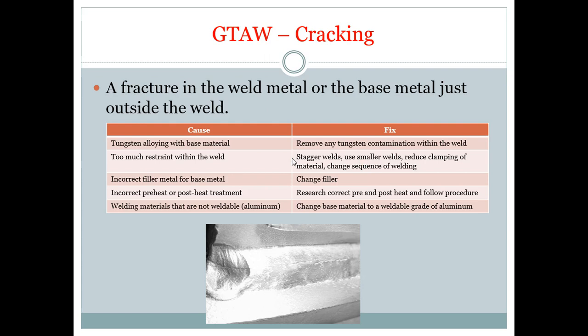And in bold red letters, we have the discontinuity of cracking. Why is that? Because cracking is the most undesirable of all these discontinuities. Cracking completely wrecks a weld. There is no saying that, oh, well, there's just a little crack in this weld, it'll probably be okay. No, a crack is going to cause the weld to continue to fail.